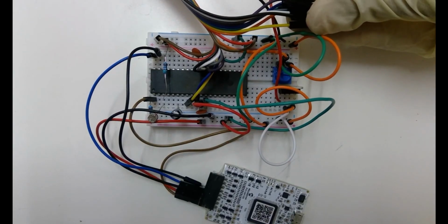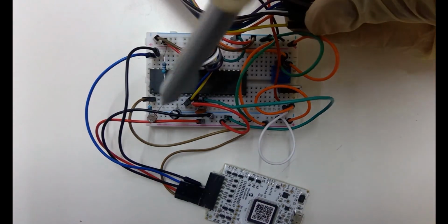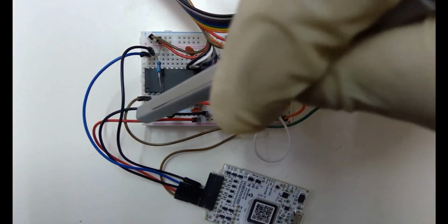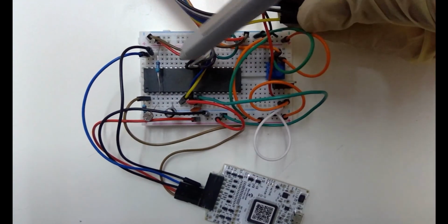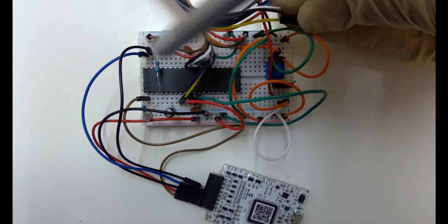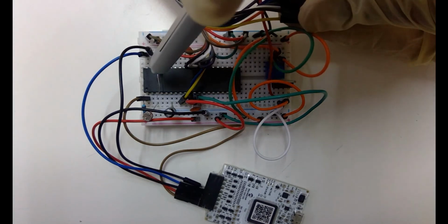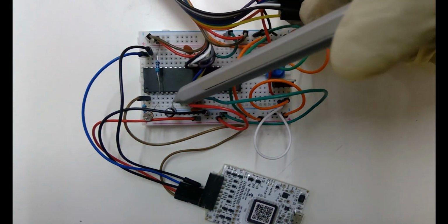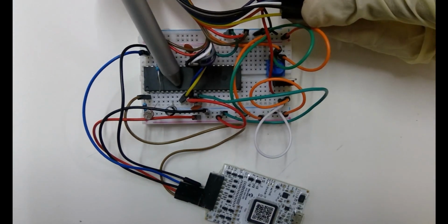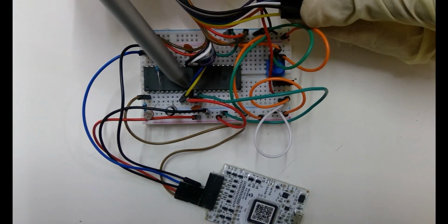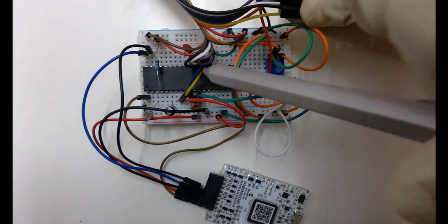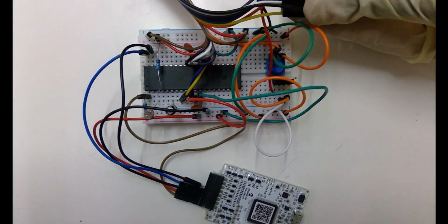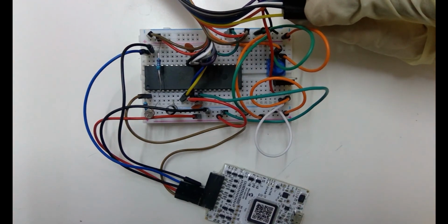If you look at it from the top, you have the LDR here on the AN1 pin, the other pin is connected to the power 5 volt, and the same pin is connected to the ground using the 5 kilo ohm resistor. And for the LCD pins, the RS pin is here, pin number 8, then you have EN on pin number 10, and on this RD4 to RD7 you have the D4 to D7 pins of the LCD.